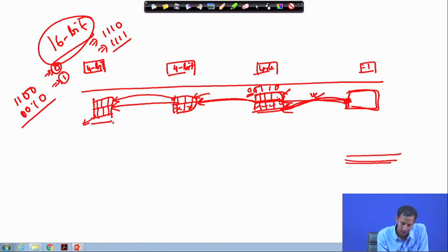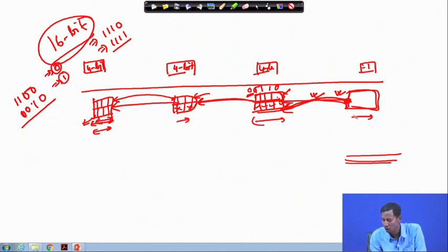So, what are the fundamentals here? The idea is that, whenever this is done, I am computing in parallel all the sum bits. Considering that the carry-in should be 0 or 1, I am computing both cases at once, since all the input bits are available to me.